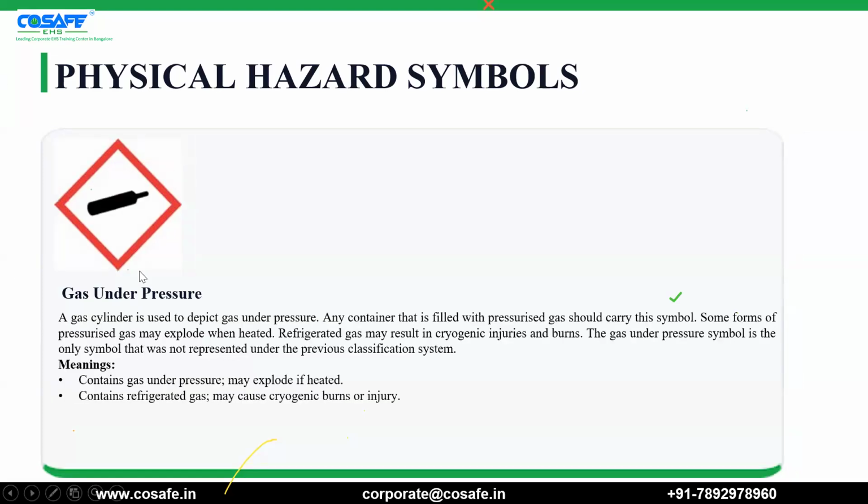Next is the gas under pressure symbol. Has anyone seen this pictogram? On a gas cylinder. Yes, it is for cylinders where the gas pressure is very high. A gas cylinder is used to depict gas under pressure. Any container filled with pressurized gas should carry this symbol. Some forms of pressurized gas may explode when heated. Refrigerated gas may result in cryogenic injuries and burns.